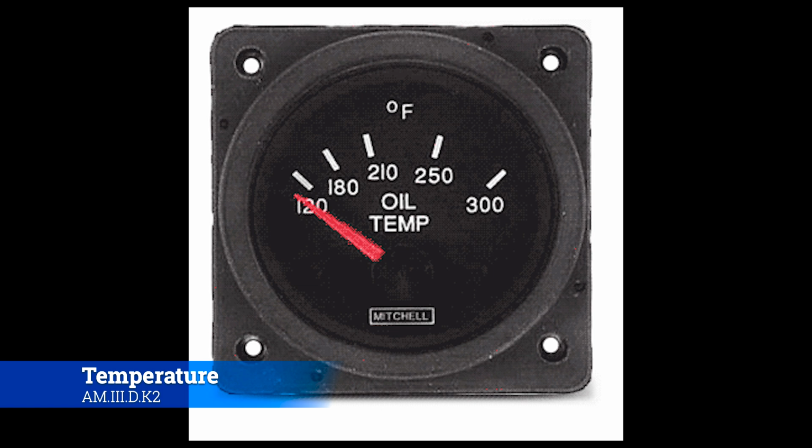The more common oil temperature shenanigan that you're going to run into is that the oil is too hot. Now, two things will lead to the oil running too hot. One, and probably the worst case scenario, is that there's not enough oil in the system. If there's not enough oil in the system, then the same oil is getting cycled through faster and faster and faster, causing the temperature to rise because it doesn't have a chance to bleed off any of that extra heat because there's just simply not enough of it.